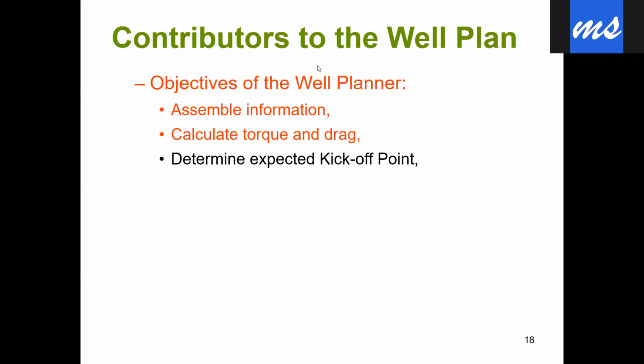But I remember that one year ago we drilled one well in south of Iraq with a high step out. It's a J shape. The step out was around 1,300 meters, and the TD was around 3,740 meters. So they are using all types of wells, S shape and J shape.